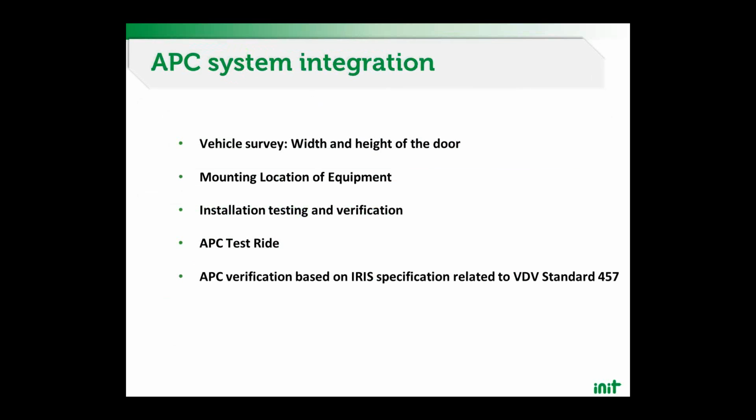For APC integration, what you need to look for is you have to do a vehicle survey. You need to check the width of the door, the height of the door. So how many sensors do I really need for this vehicle type? The mounting location, do I need an external bracket? Can I install my sensor already in the doorway, or do I need to manufacture some brackets? Then the installation and testing and verification.